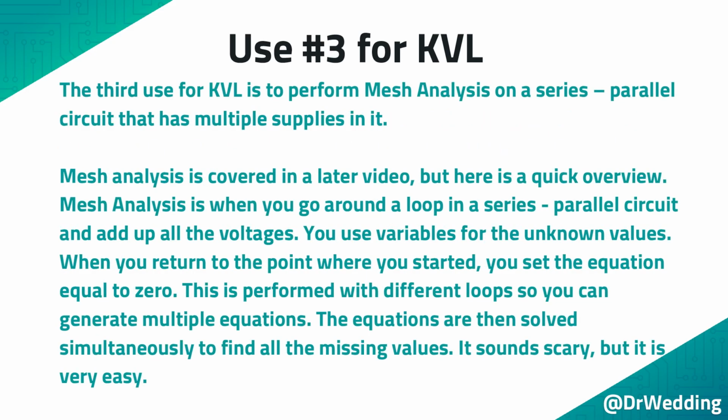The third use for KVL is to perform mesh analysis on a series, parallel circuit that has multiple supplies in it. Mesh analysis is covered in a later video, but here is a quick overview. Mesh analysis is when you go around a loop in a series, parallel circuit, and add up all the voltages. You use variables for the unknown values. When you return to the point where you started, you set the equation equal to 0. This is performed with different loops so you can generate multiple equations. The equations are then solved simultaneously to find all the missing values. It sounds scary, but it is very easy.